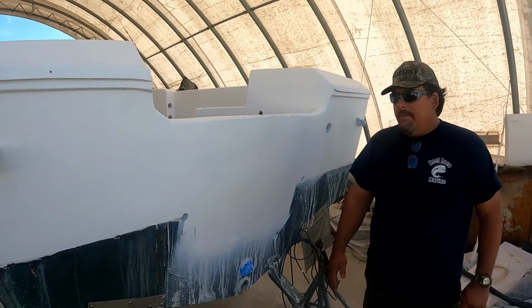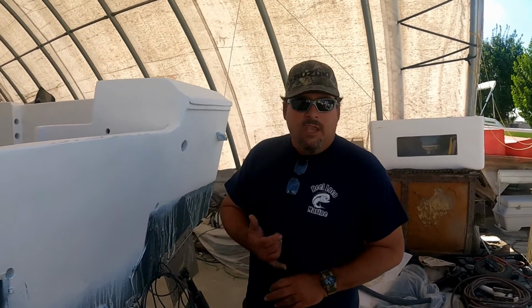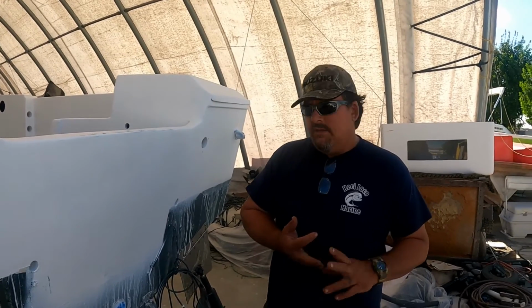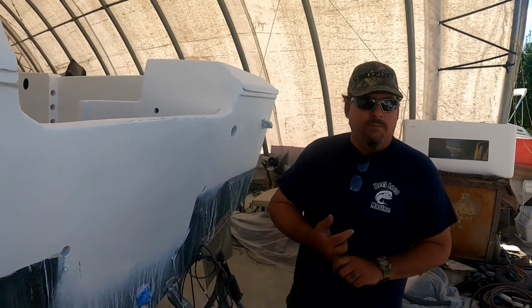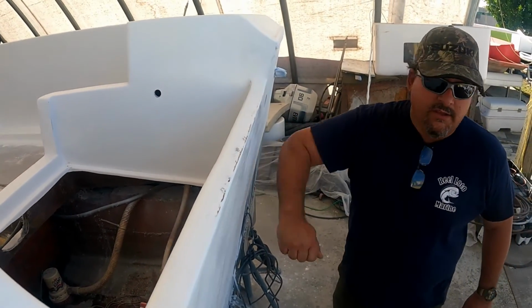With which material do you fill the transom? Well, you're going to use biaxial, and you're going to use marine plywood. Correct. Or you can use a core. And this guy didn't want to spend the money, so he went with the marine plywood. This is the thickness. It's pretty thick. All right.